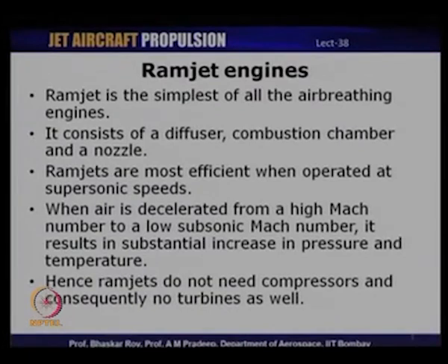And ramjets, by their very construction or the thermodynamic principles, are most efficient obviously when they operate at supersonic speeds, and at such very high speeds, when the air is decelerated from a very high Mach number to a very low subsonic Mach number, it results in a substantial increase in static pressure and temperature, which means that ramjets do not really need any compressors. Since they do not need any compressors, you also do not need any turbines in a ramjet, because turbines in an air breathing engine are meant primarily to drive a compressor. In a ramjet, you do not have compressors, so you do not need turbines as well.